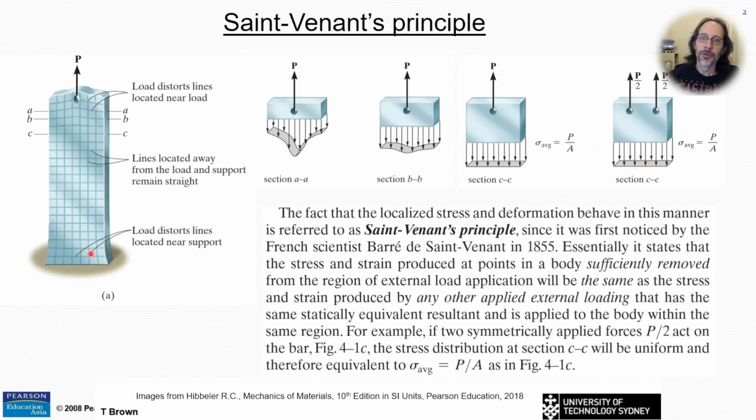You can see at the bottom of the picture on the left here, we've got a built-in support. If we had a pin connection at the end here, then the stresses and strains around that support will be different from a built-in connection, but at a small distance away, they'll be uniform and independent of how that bar was supported.